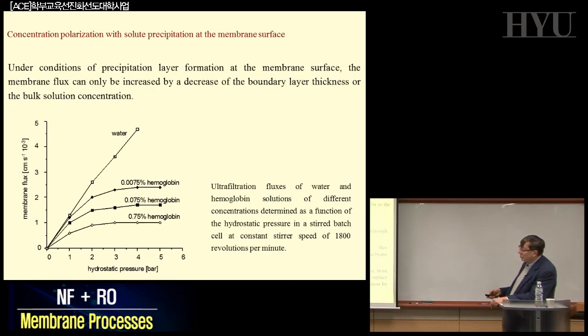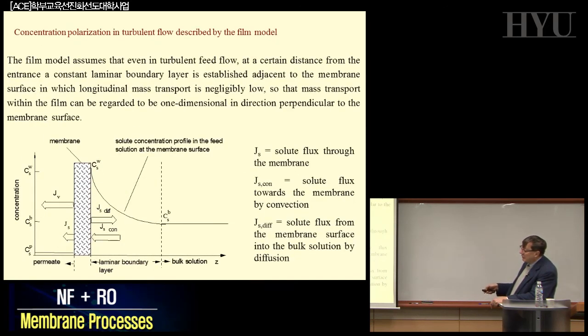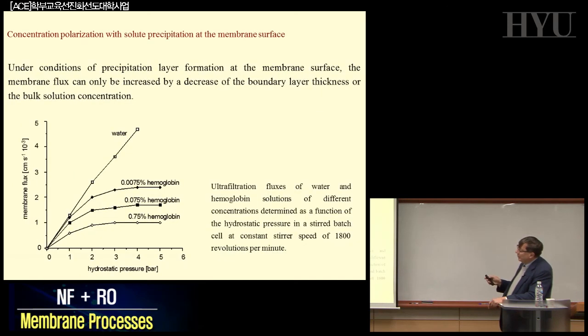And you just have to integrate over the thickness of your system, assuming that the concentration at this level is exactly the same as in the bulk, and here you have the concentration at the wall. What you normally assume during your integration is a linear behavior, not of the concentration profile, but you can assume linearity here, so you can have a nice expression for the concentration at the interface, if you know the concentration in the bulk.